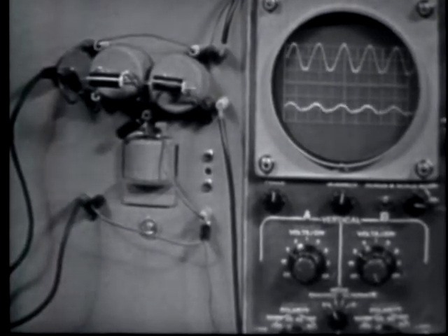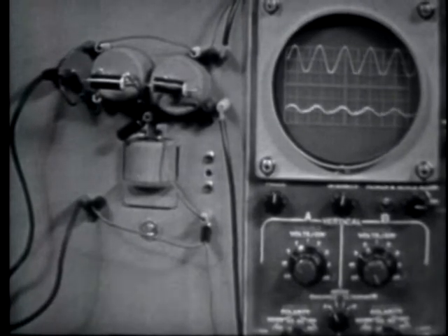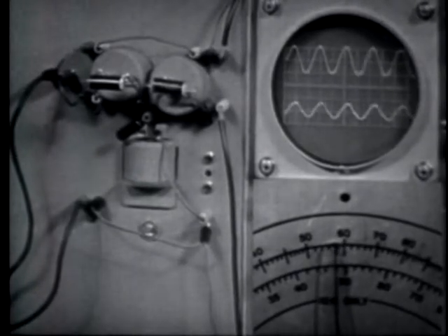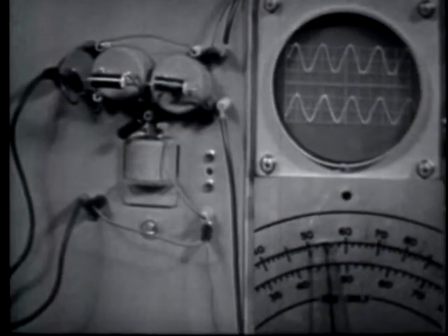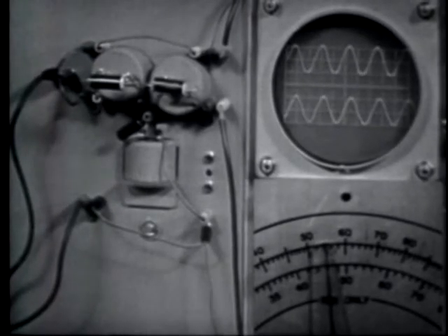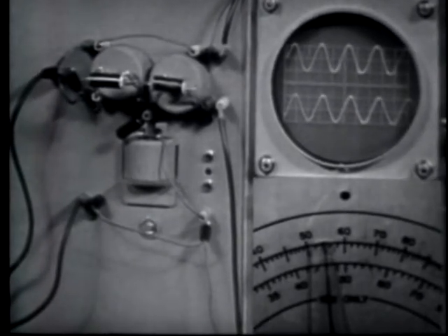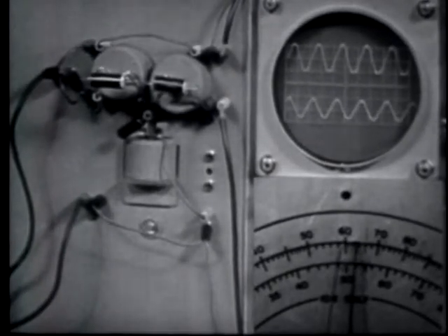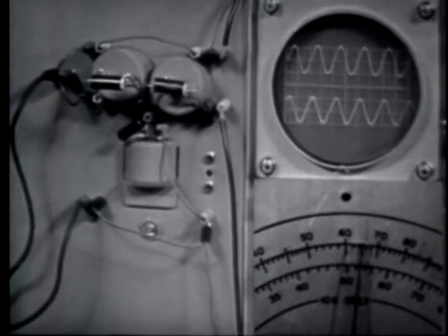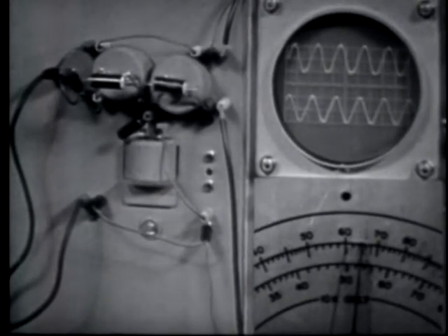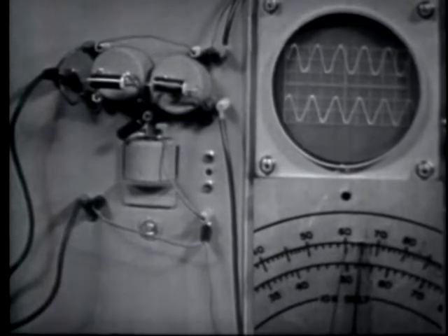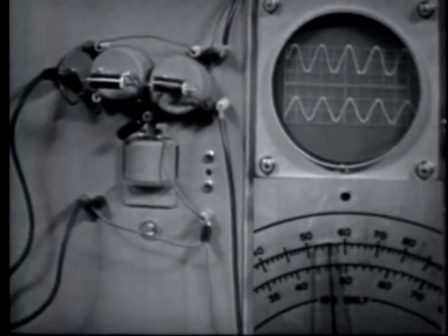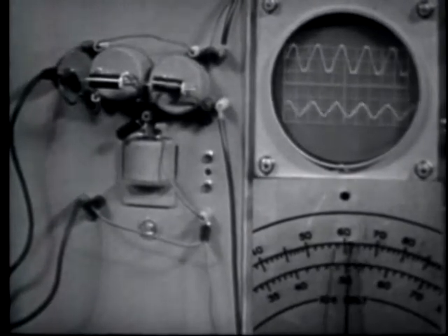Now let's check the frequency response of this circuit and see if we have indeed improved it. All right. Notice now that I only have to go down to about 550 hertz, and I have maximum output from the filter. The same is true on the other side of the frequency we wish to reject. At about 650 hertz, I now have maximum output from the filter. So I'm now rejecting a band of frequencies much closer to 600 hertz. I have indeed improved the frequency response of the filter.